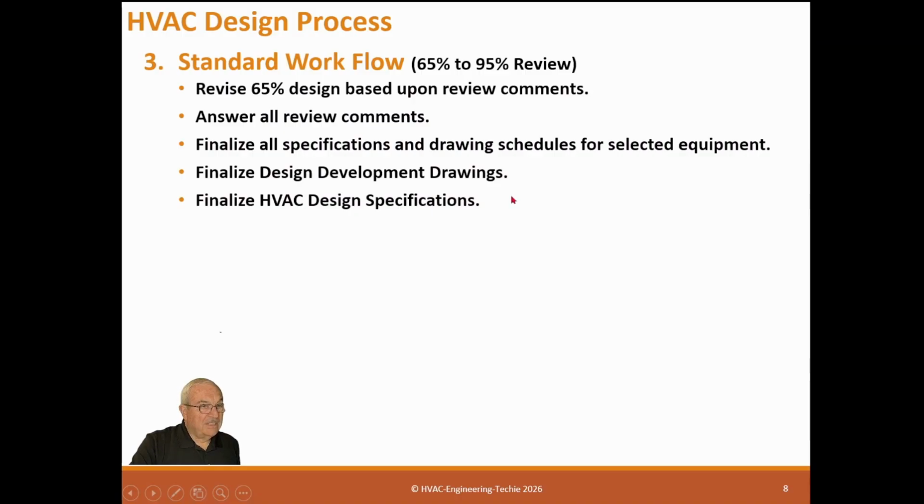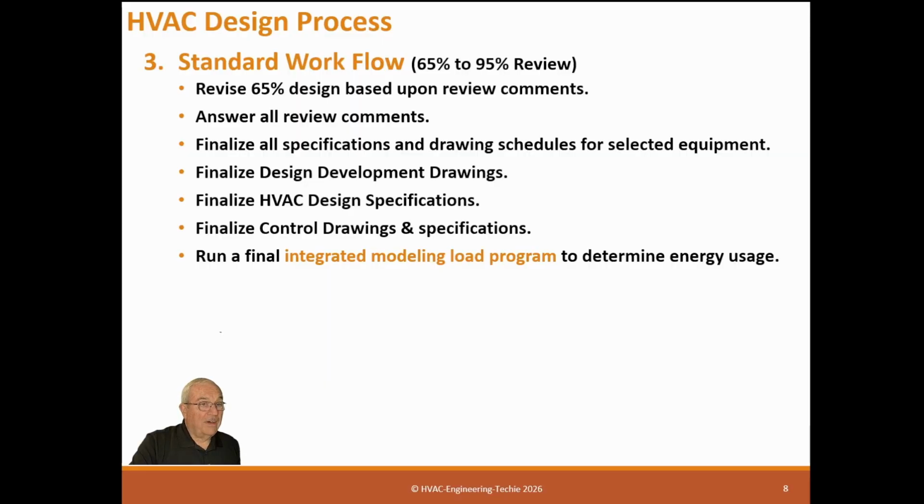Finalize HVAC design specification, finalize control drawings and specifications, run a final integrated model load program to determine energy usage. So at this point is where you're going to run that final model, because you have all the horsepowers, everything is settled here, so you need to do that. Review 95% documents for full communication of the design, and we will talk about this.